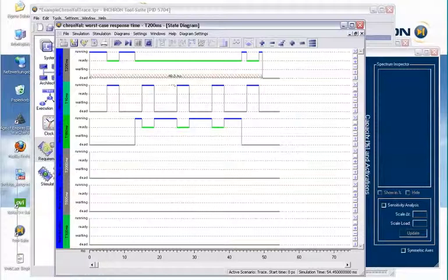For example, if you just think of a slight phase shift between this and that process here, that would all lead to the same response time. So this is not the real worst case situation, it is a worst case situation that leads to the worst case response time. And you see that it is highlighted a bit in red as well, because it violated our requirement.